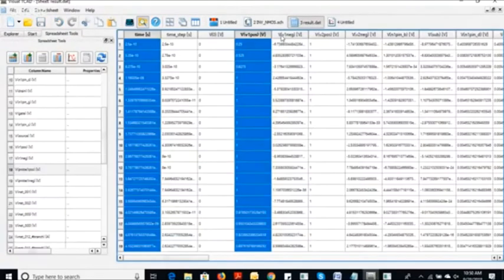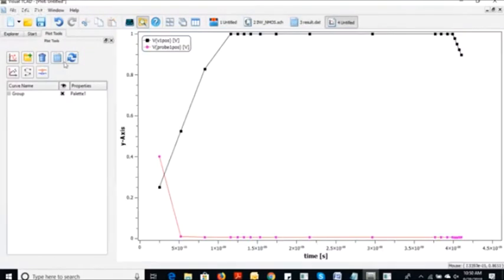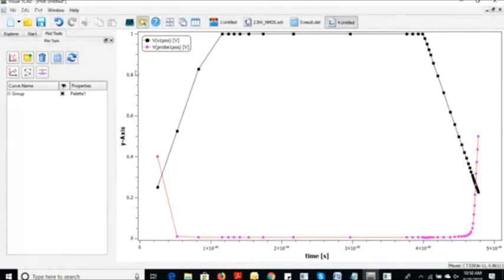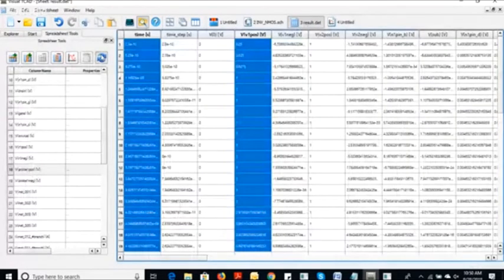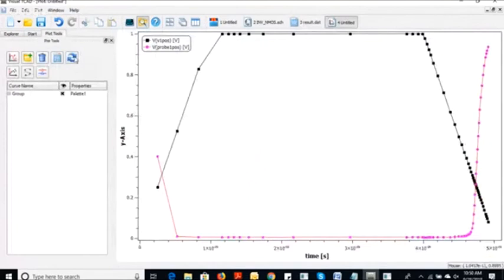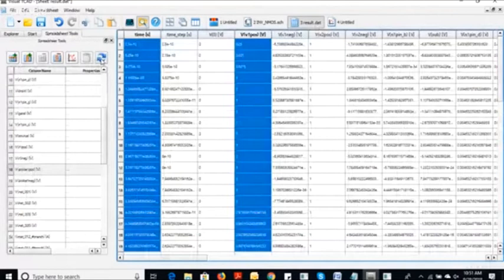During runtime, we are just updating the results. And we see the input is black and output is pink color. It's inverting. We refresh it. This is the initial condition, so we can ignore it. That's why I'm taking 2 pulses. I'm doing simulation for 16 nanosecond.